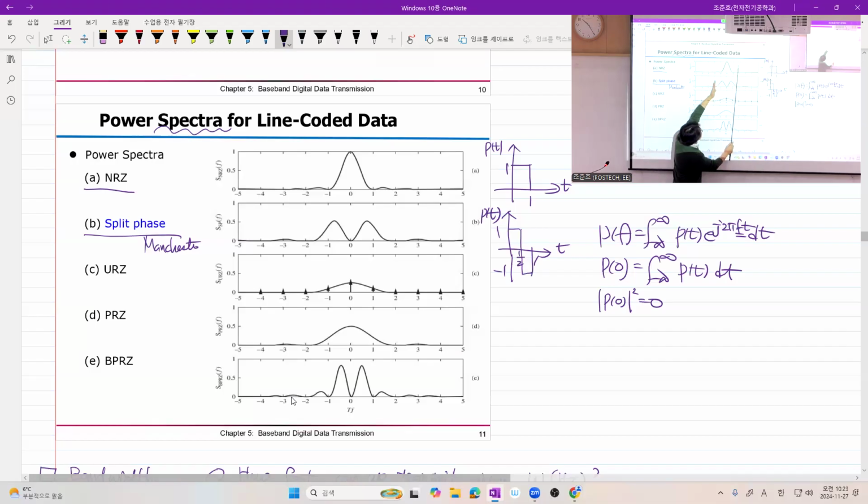Then outside this plus minus 1 band, what about the power spilled over this band for NRZ? And what is the portion of the power spilled over this bandwidth in Manchester code? So we may just vaguely say that Manchester code must occupy larger bandwidth than NRZ.